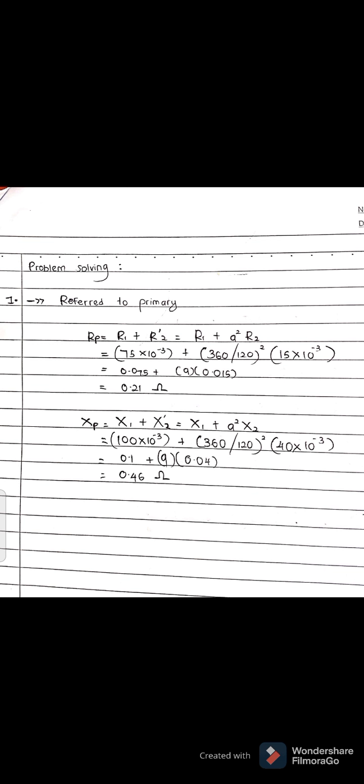equal to X1 plus X2 referred to primary, which is X1 plus A squared multiplied by X2.